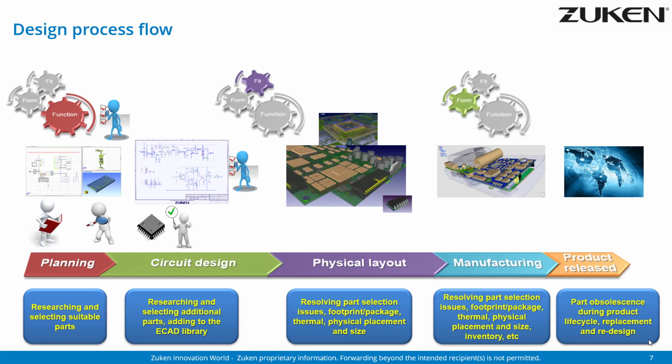size, the height, the weight, etc., how it fits in the enclosure and on the printed circuit board, all need to be considered. Additional design elements such as heat sinks, the assembly and the location on the board all need to be considered. And when we get into the manufacturing, much more it's the combination between the ECAD and the MCAD and how the components fit in the enclosure, spacing, etc.